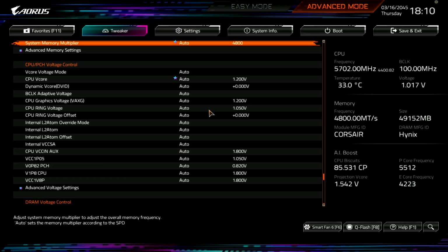So if you start undervolting by setting a voltage offset at the voltage regulator, the CPU isn't aware that there's an offset applied to the voltage. So it sees that, hey, the voltage is 100 millivolts below where it's supposed to be. Therefore, I'm probably pulling way too much current, and it starts downclocking, which creates the performance drop.